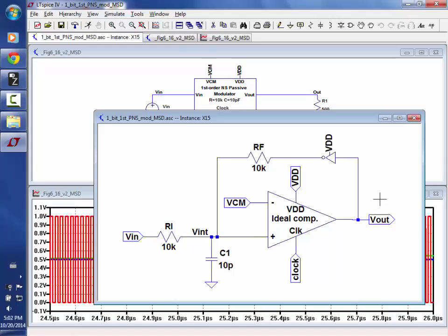So if I have 10, 10, 10 here, and it's feeding back, I can get the situation where the amount of charge that flows in here, because this is varying, is equal to the amount of charge that flows back through here, and it sets up these limit cycles or oscillations where it just bounces back and forth and it's happy. It's not that this isn't moving and my input's putting in a fixed charge; this is moving back and forth and I get the same amount of charge. So did that make sense to anybody?